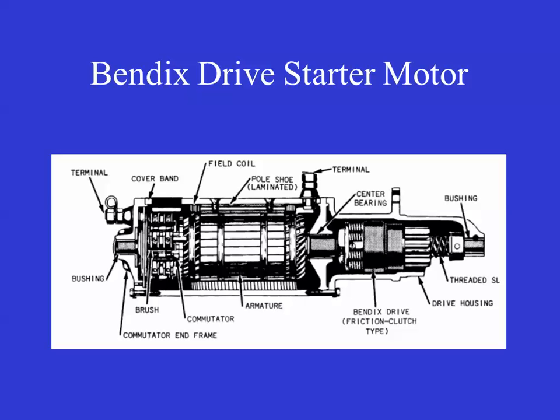If the engine starts and you start revving the engine up, you would over rev the starter motor, and the windings would come out of the motor. Most of these starter motors are DC. Most of them today are still a series type DC motor.